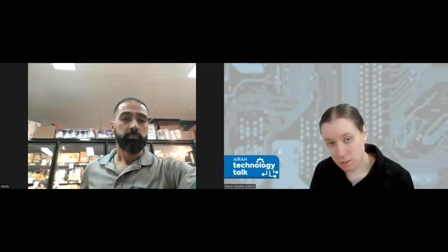Thanks, Morty. And just another question for you: the high pressure is reading lower than the low pressure side on the reading that you had earlier up on the screen. Is that because we don't have a reading on the liquid line temp? That's correct. At this evaporator, we didn't have a port to connect to. I didn't see any that I could connect to.